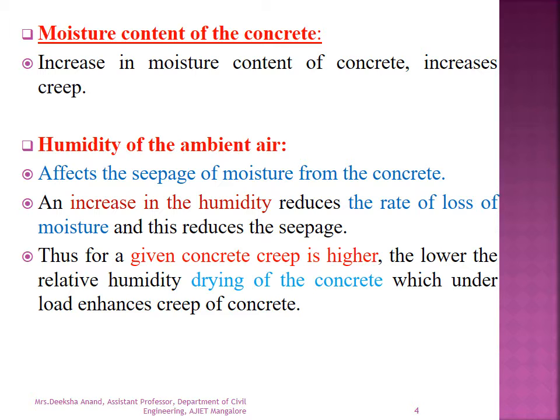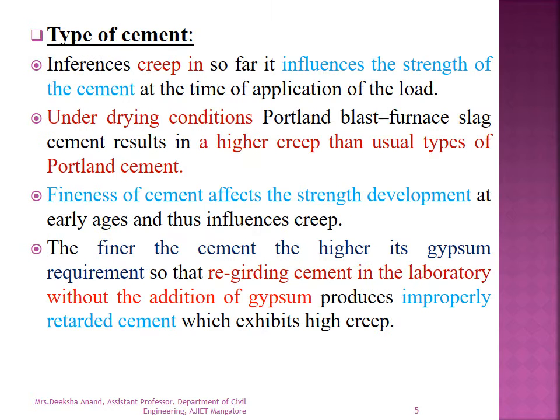Next, the type of the cement: the finer the cement, the higher is the gypsum requirement, so regrinding cement in the laboratory without the addition of gypsum produces improperly retarded cement which exhibits high creep.